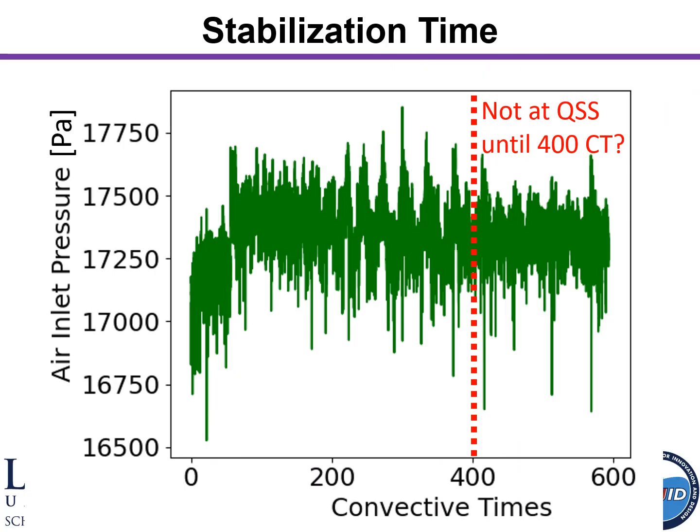Another super important feature for any unsteady situation, whether you're using CFD or an experiment, and I can't stress that enough, is that you need to allow the model, or the experiment, to become quasi-steady state before you consider it statistically stationary, so you can begin collecting data.